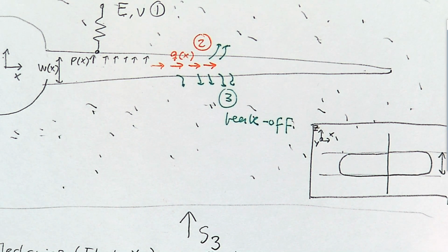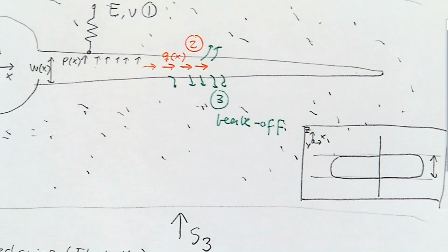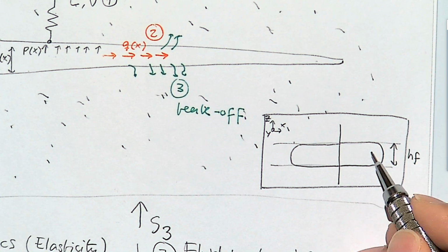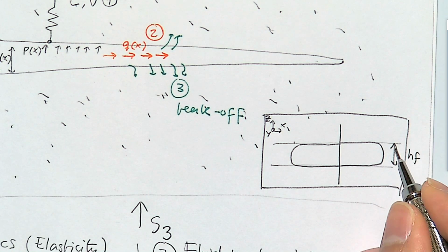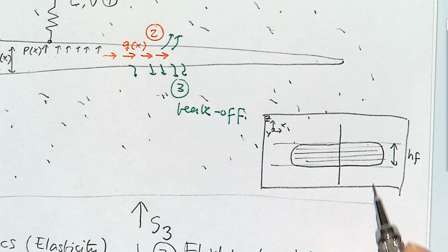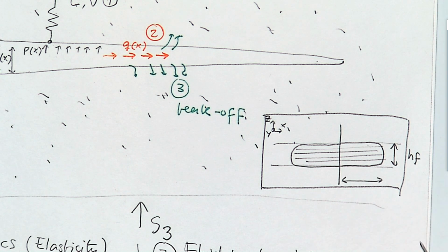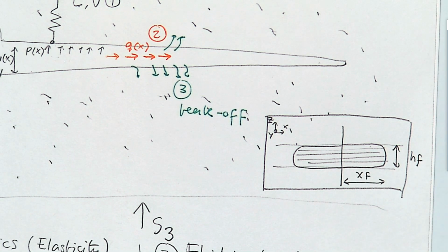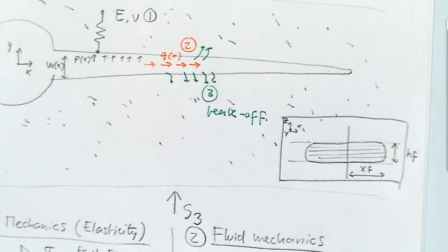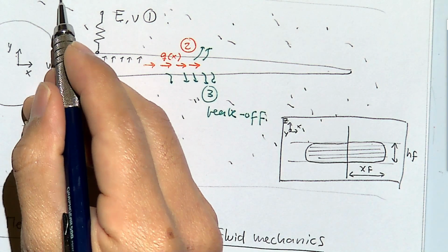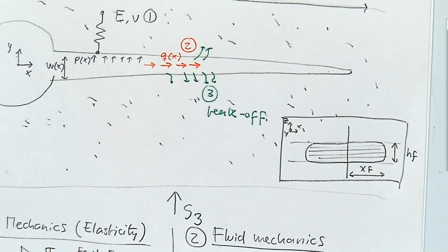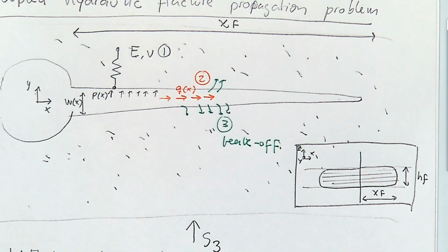based on, we're going to see, that depends a lot on horizontal stress. And the height of the fracture is going to be the distance from here to there, where this is the fracture, and this is what is called the fracture half length, which in our model goes from here to there, from the beginning of the fracture up to the tip.